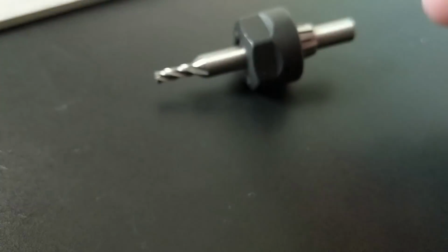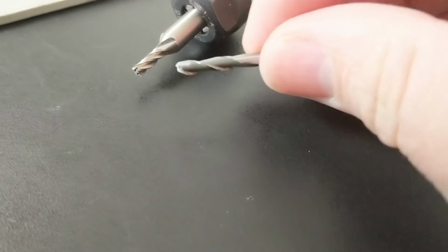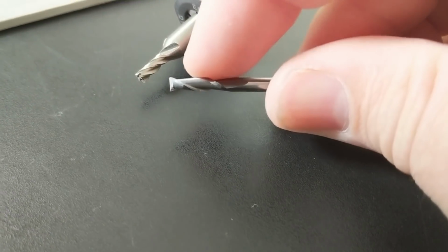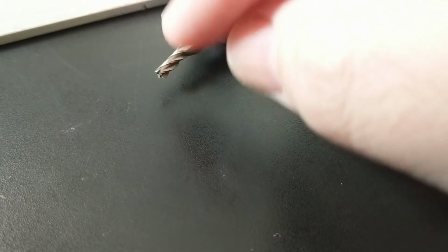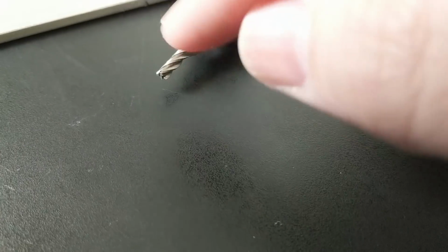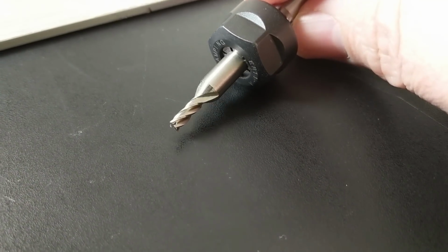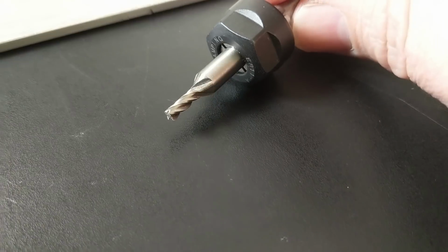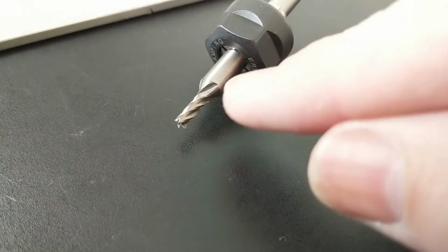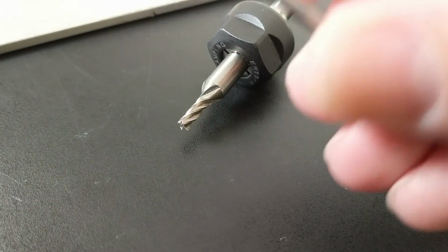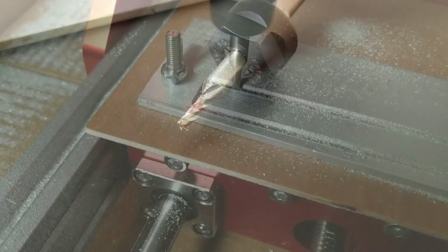Yeah, same size cutter, more or less. Actually, this is an 1/8 inch, so that's 3.2 millimeters, and this is an actual 3 millimeter cutting head. The problem with this one is that it's got 4 flutes. It really changes up the behavior of the cut to have 4 flutes. So I'm hoping that this is going to work. I'm going to try to stay away from 4 fluted bits on this machine from here on out. But this is the only bit that I have that's not long and skinny like this one.